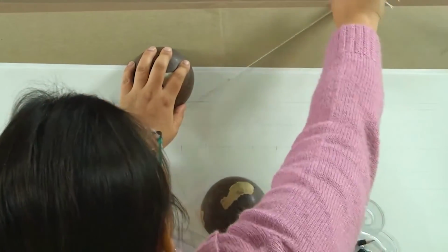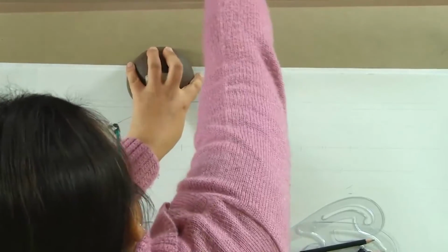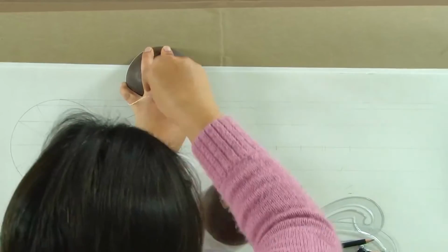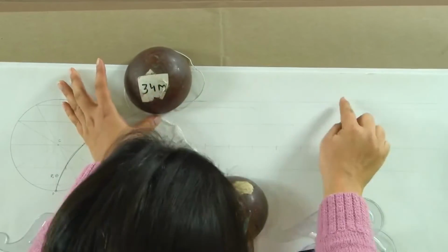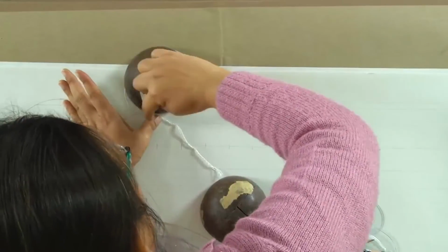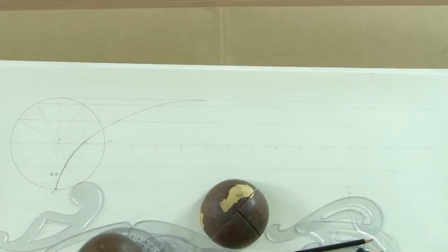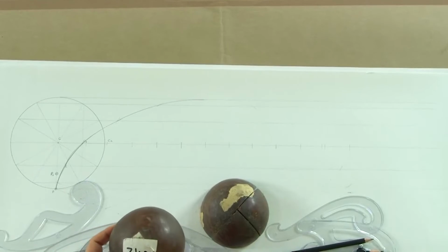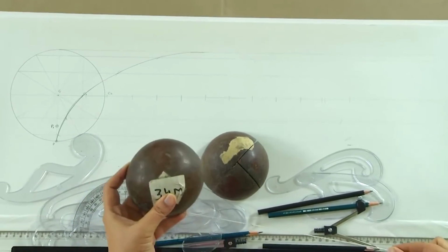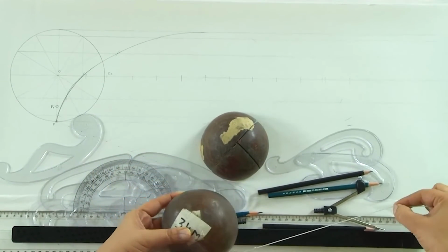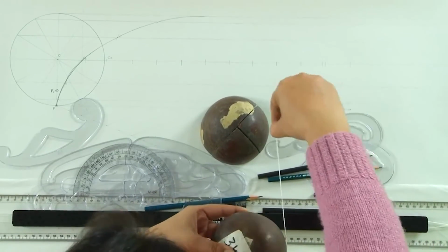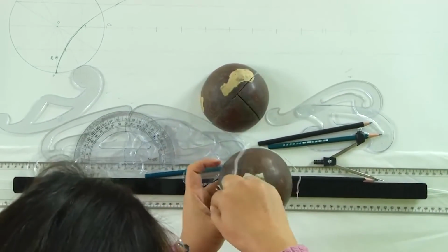If we keep moving this path here and the thread gets wound, and once it comes back, it is back to the original point, but the path that it has traced is the involute of this thread. The only thing that we have to assume here is that it remains in tension all the time and the length of this thread is equal to the circumference or the perimeter. So, this is how the involute would be drawn.